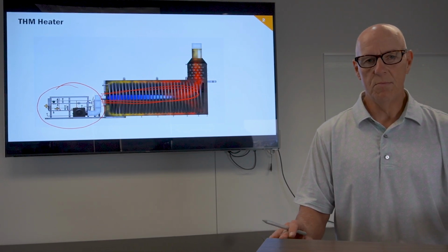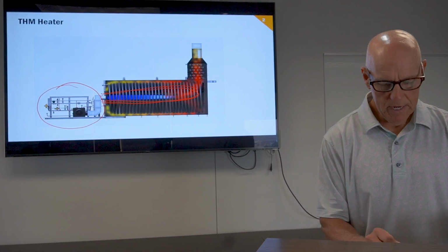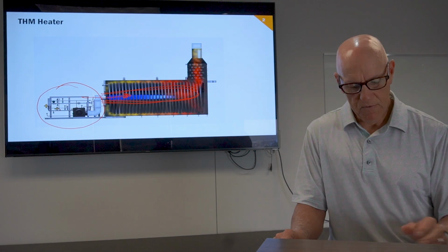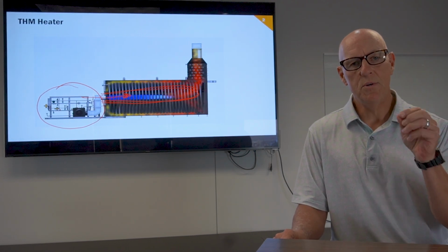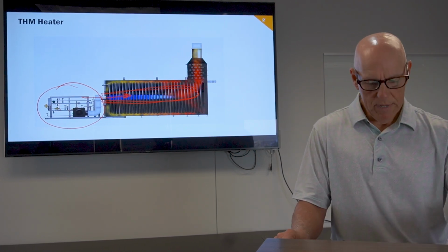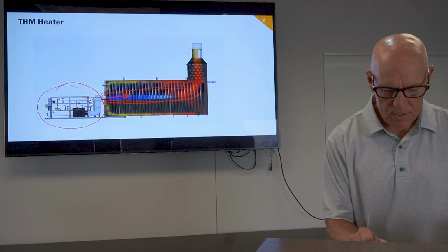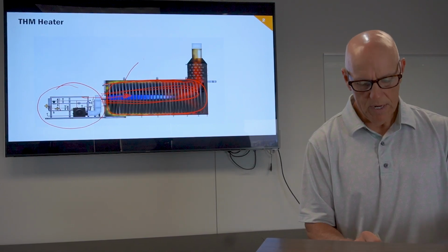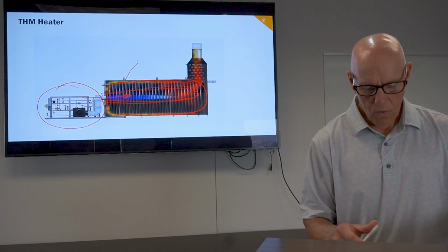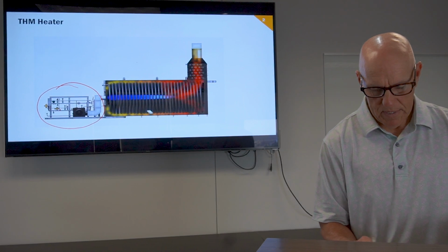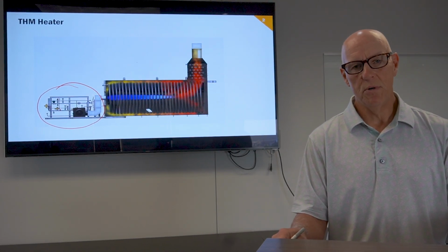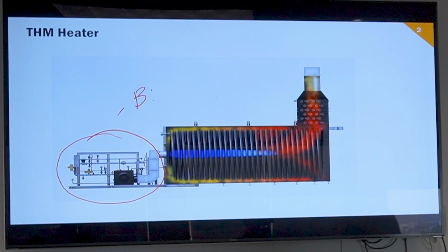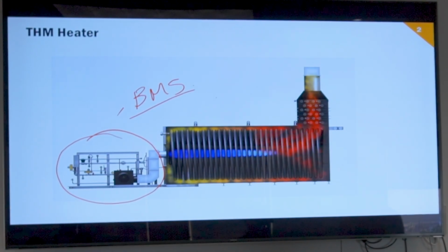One of the safety systems is a purge sequence, meaning before you would inject fuel gas into this heater, before you want to spark that pilot to introduce an ignition source, you want to make sure that everything's cleared out, that there is no gases inside of here mixed in with the air. Otherwise, you could have an explosion on the heater. In a natural draft heater, that becomes a little bit difficult. How do I ensure that there's no gas that has leaked through my burner management systems and gotten into that heater before I spark that pilot?